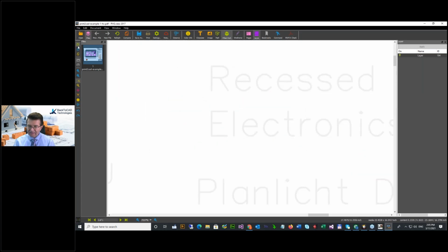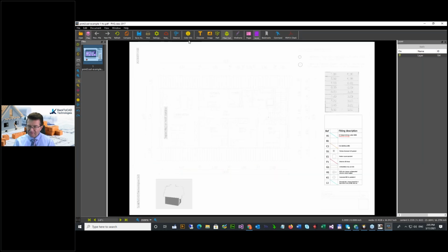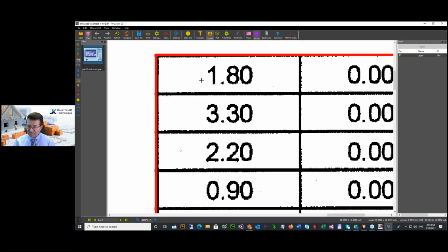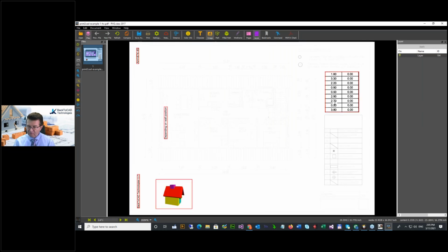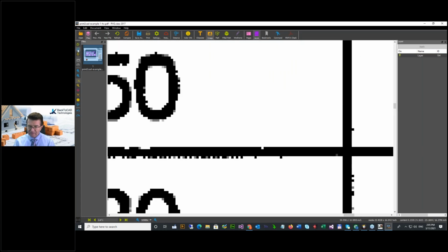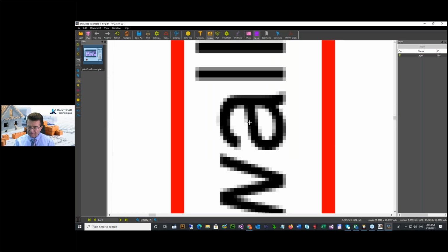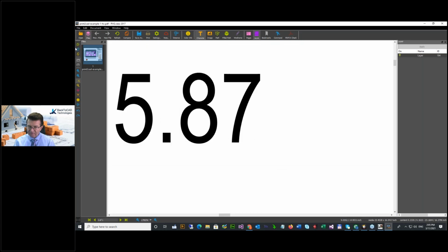Separate hatches. Separate field paths. This text, for example, is a field path. And separate raster images. You see, this is a raster image. This is not a native PDF. This is a text as a raster image, and this is a line as a raster image. If you zoom in, you can see it. Here, if you zoom this L or this A, you can see this is not a native text. Now, if you go here on character and zoom, you see this is a native text.